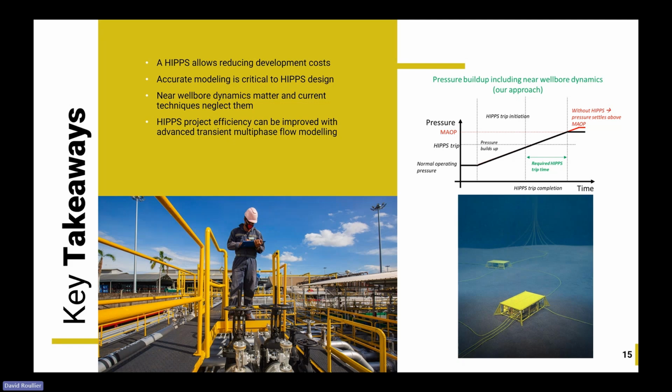And then it comes into the hand waving theory. If you're depacking with a choke, the choke has a very small CV, so then you know what's that critical flow from that choke opening, and what's the fastest you can open your wellhead choke? It might or may not be, but when it is, this tool is also applicable.